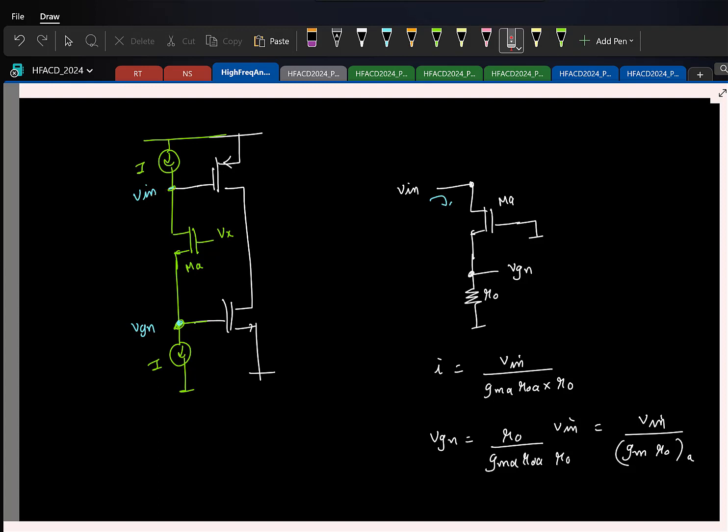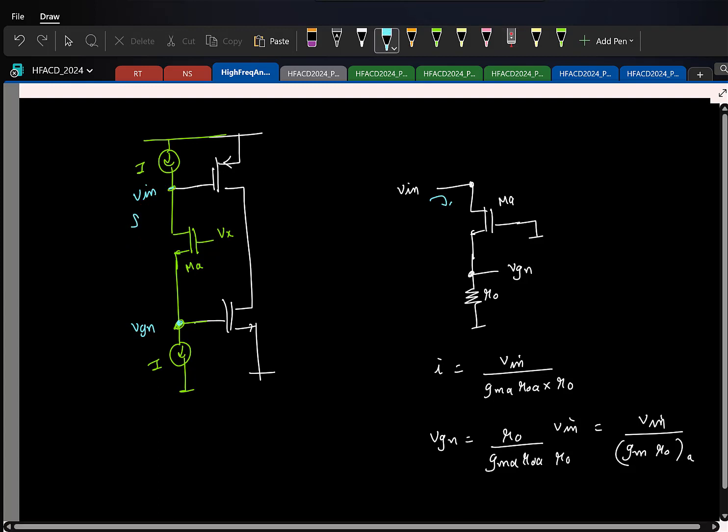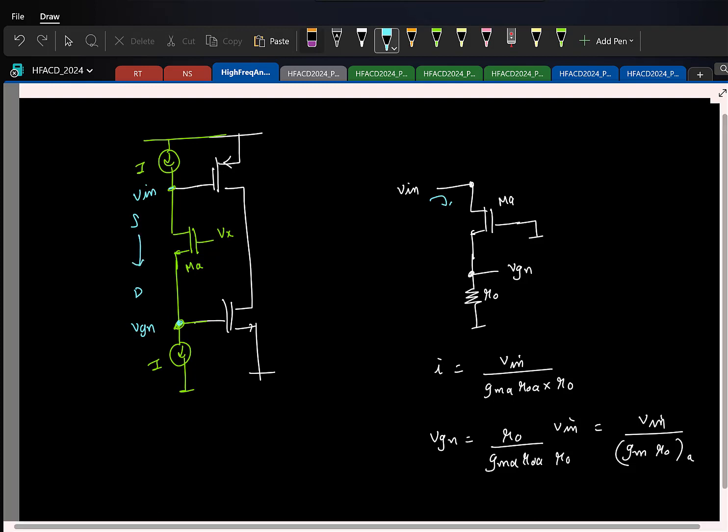And preferably, I mean, I don't want to use a resistor because I want to track things. So I might want to use a transistor. So what terminal of the transistor can I connect here so that the resistance reduces? I can connect a source. So somewhere source should come. So drain should come here. Current is flowing in this direction. I should use PMOS. So which means I'll do, let us say this is connected to some voltage VY. We'll see how we can generate it later.